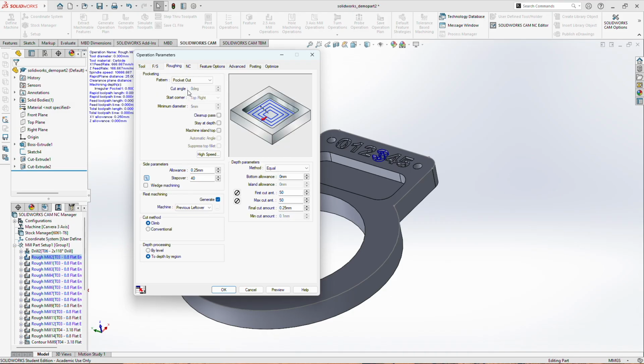Here we can go ahead and adjust our roughing. Now, if you have a roughing pass, SolidWorks will automatically not finish all the way up to the part. So, for example, you can see that there's an offset of 0.25 millimeters on a roughing pass, which means that it's not going to actually machine the entirety of your part because it wants you to then do a second tool pass and then do a finishing pass, which for high precision and really high detailed machining is the right approach. But in general, for a quick prototyping like part, you can usually get away with just one pass.